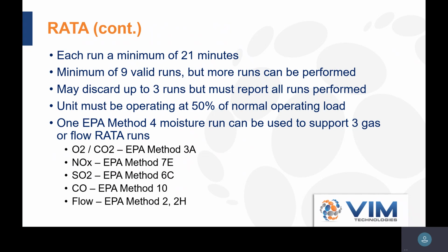It's important to consider your 50% of normal operating load. So you need to know what your normal operating load is, and just ensure that you're at least 50% of that operating load when the RATA is performed.